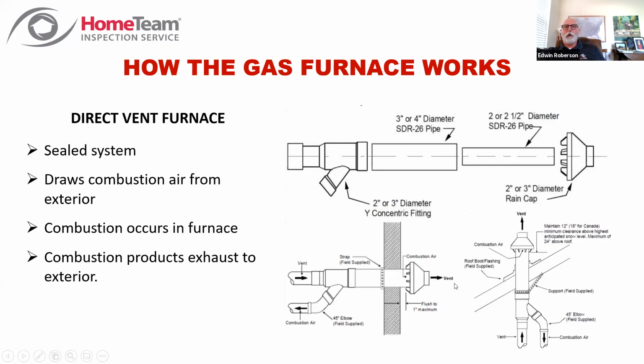And you don't need any air for combustion from the living space. In fact, in houses where you have sealed crawl spaces or sealed attics, and you have a combustion system, you have to have a system like this. You have to be able to pull combustion air from outside the home.